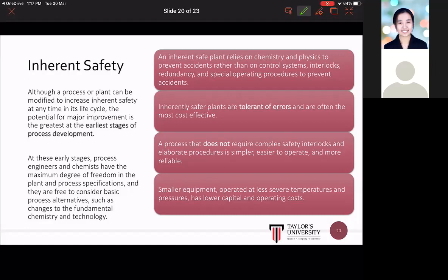It's best that inherent safety is built in during the design phase, mainly when you do your process plant design in semester 7 and semester 8. You will start looking at, okay, I have these chemicals, this one is so toxic. Just a teaspoon of it, when it evaporates, people will die, and you may want to change that chemical. You may want to say, in that case, I don't want to use that chemical, maybe I use a replacement chemical. Those are inherent safety, the things that you can do at a very early stage when designing a new plant.